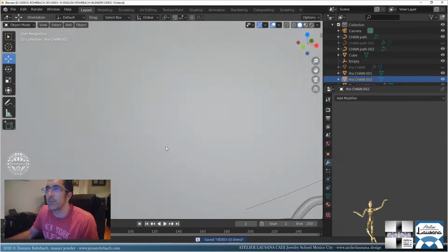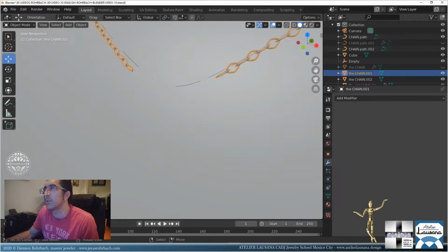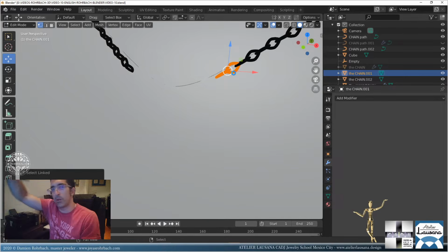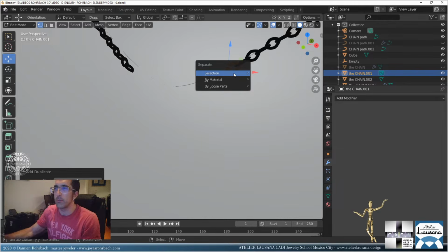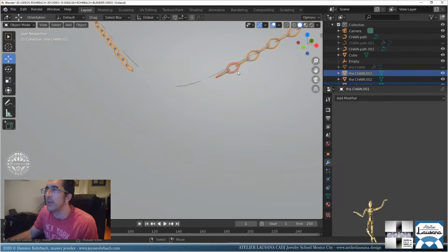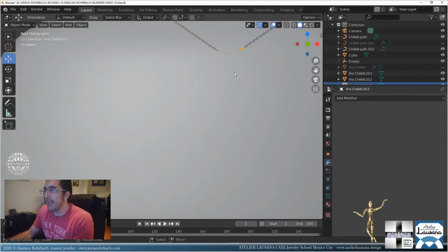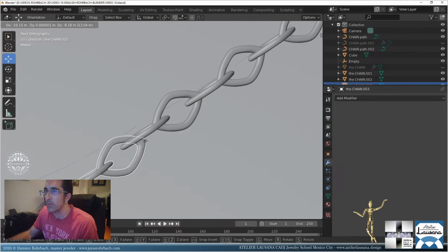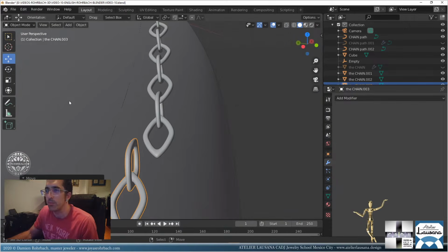Okay, now let's go on the front of the chain. Let's try edit mode, Alt A, L, Shift D, Enter, and P selection. So I'm extracting 2 links. Let's go out here. All right, let's take these guys. The numpad point key zooms in. It's very cool. All right, so now let's complete the chain.